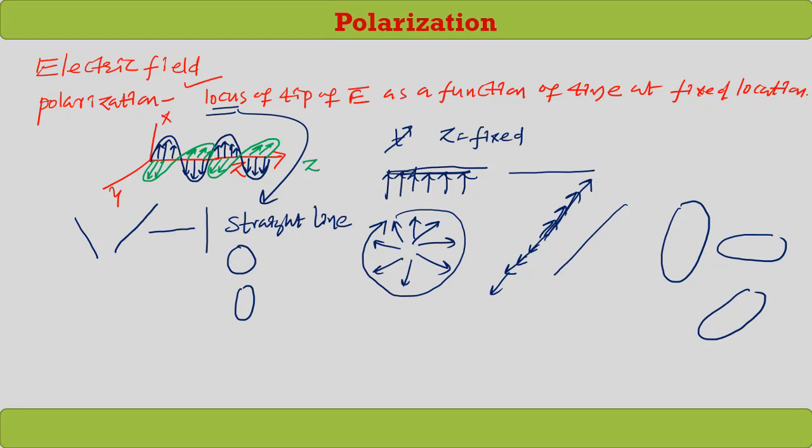That means this type of polarization is said to be linear polarization. So in case of the linear polarization, we have different types. Okay, that is a horizontal polarization like this, vertical polarization like this, and simply linear polarization with slope 1 or positive slope, and here slope is negative. So all these things will come under linear polarization. Now coming to circular polarization. Okay, if the locus is circle, then we can call that a circular polarization. That particular electromagnetic wave is consisting of circular polarization.